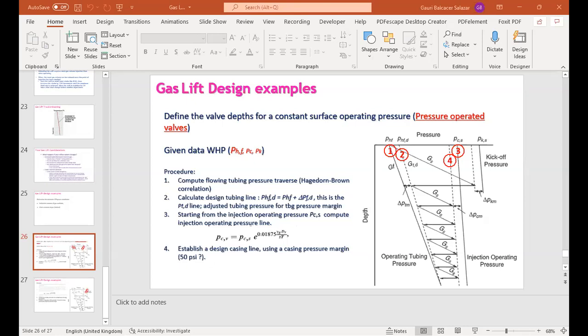And so the IPR, using this IPR equation, the maximum rate is 1,500 standard barrels per day. The average pressure is 2,000. Tubing is 2.5 OD, or 2.259 ID inch. The packer is set at 5,000. Wellhead pressure is basically 200 feet above the mid perforations.